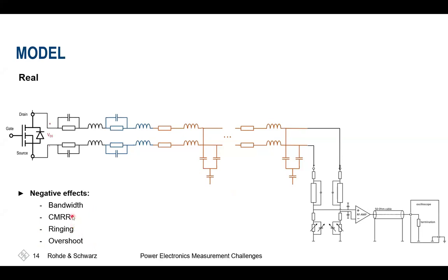So the first tip from my side would be, if you think you might have an issue with your setup, you could prove the effective common mode rejection ratio by measuring plus and minus at the same point. So having both of them clamped to source, let the device switch and look on your screen at how much ripple is effectively left on your oscilloscope screen, because this gives you immediately the common mode rejection ratio on screen. So you don't have to do any maths. You immediately see how large your effective common mode rejection is for this current example.